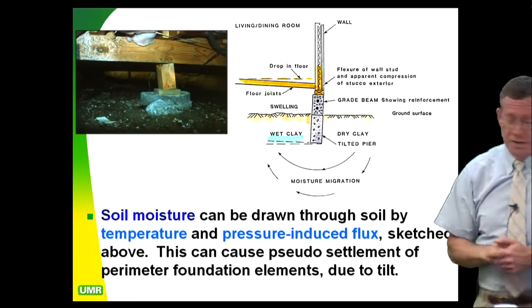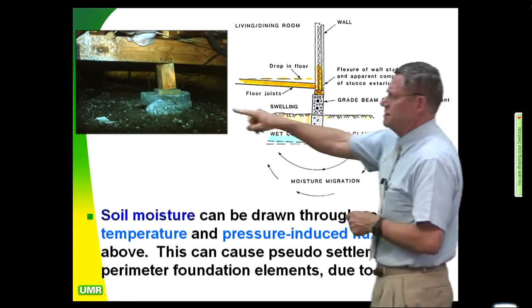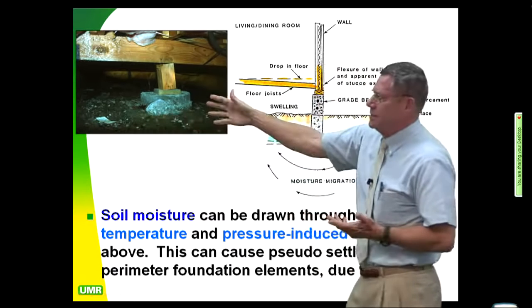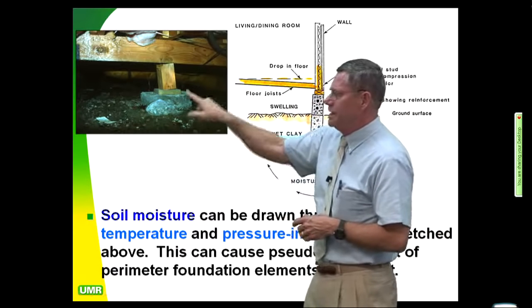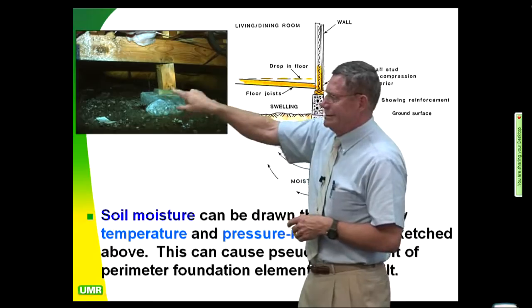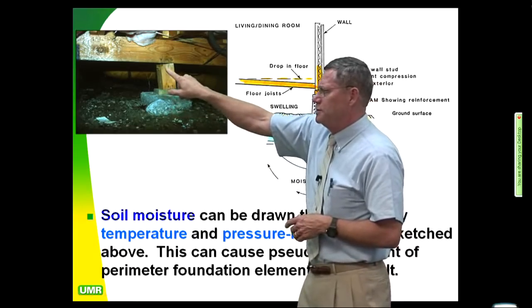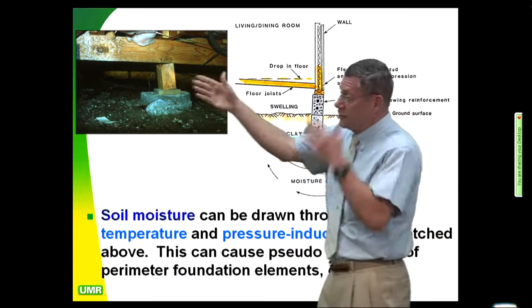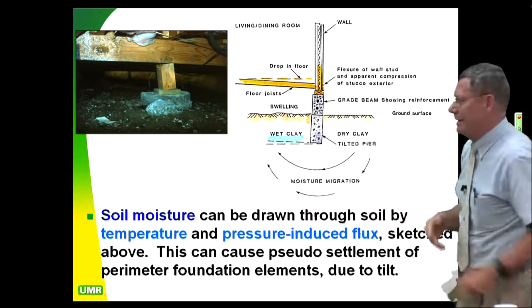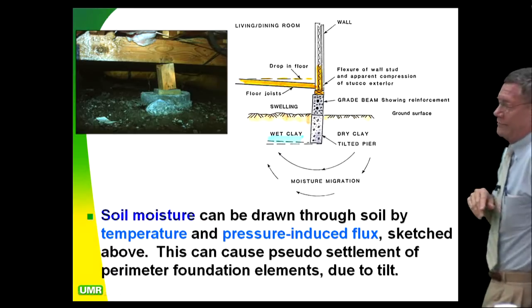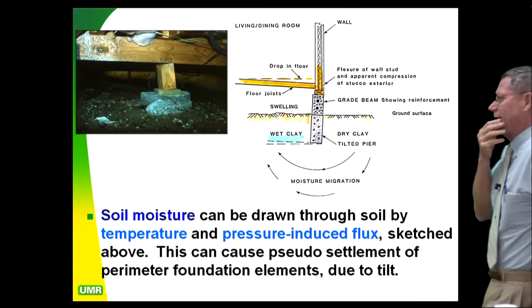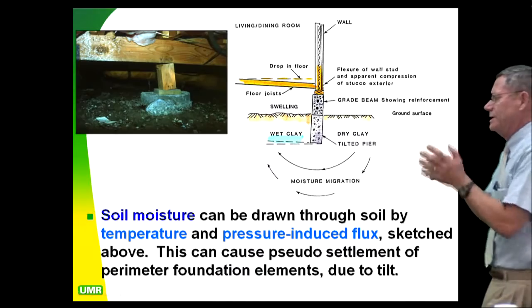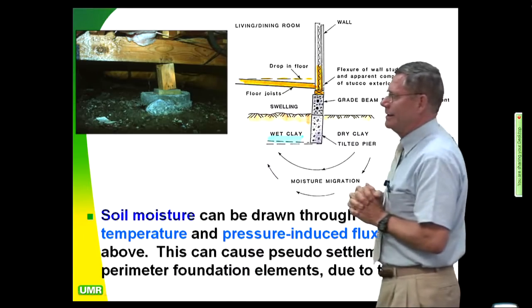Well, here's what happens when you crawl under a house and you look inside of it. This is in Silicon Valley, San Jose. Typical here, they have these 6-foot deep piers. They have a 4x4 treated wood post here, holding up a girder, and you can see the thing's rocking. And they're in earthquake country. So you're looking at that going, how old is this place? Well, it's 4.5 years old. How much did they charge for the house? $900,000. $900,000, and I couldn't even get to year 5 without having framing integrity checks? No, wasn't able to get there.